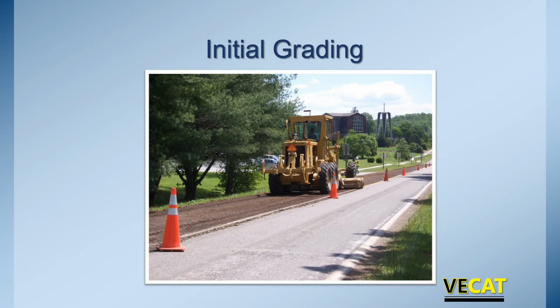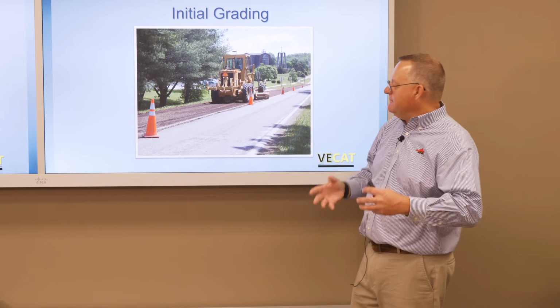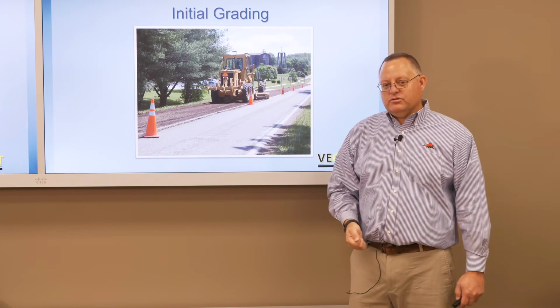And now we come through with the motor grader. So we're doing that initial grading to get some slopes back. If we need some cross slope, we're putting it back in. Could take several passes of taking the material that's been compacted with that initial sheep's foot. Maybe we're clipping off, but we're moving material around, maybe moving material to the outside, depending on what's needed on that project. But now we're doing the initial grading.